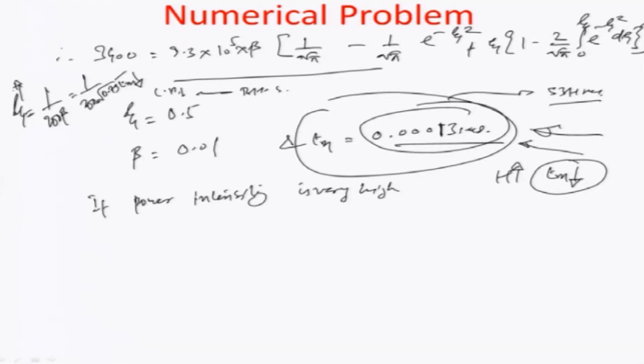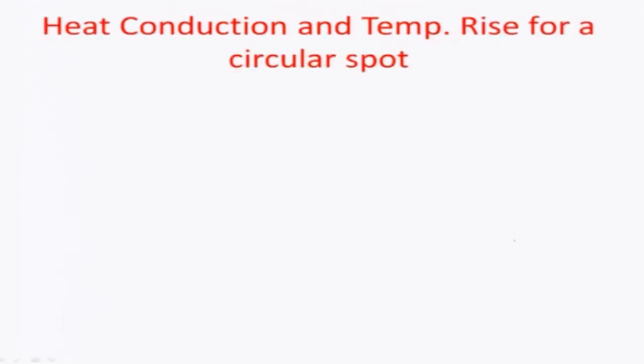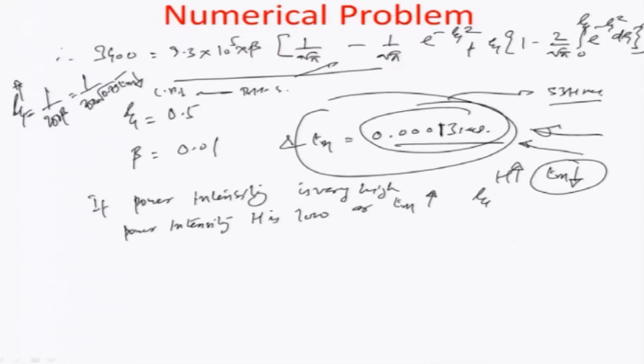So, some changes should happen in this particular equation based on if the zeta is either reducing or increasing. So, supposing there is a case when the power intensity of the beam is low, or time of machining is high, and subsequently the zeta is falling down here, zeta goes down.